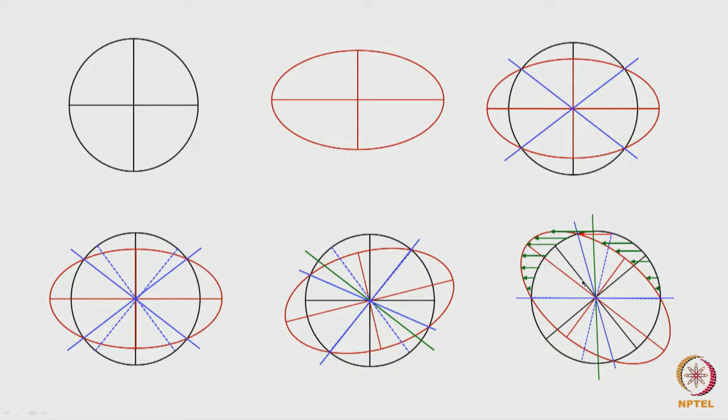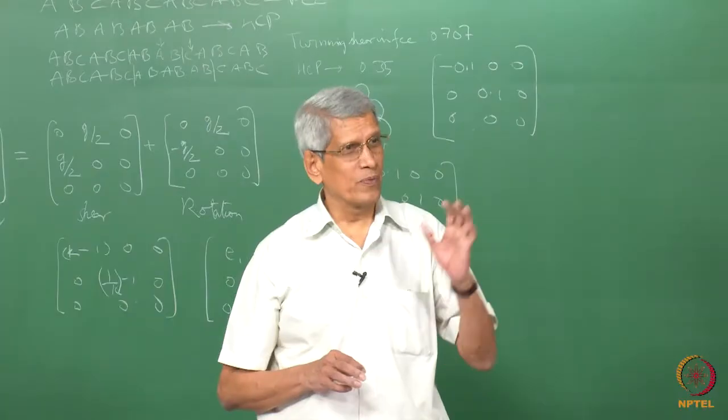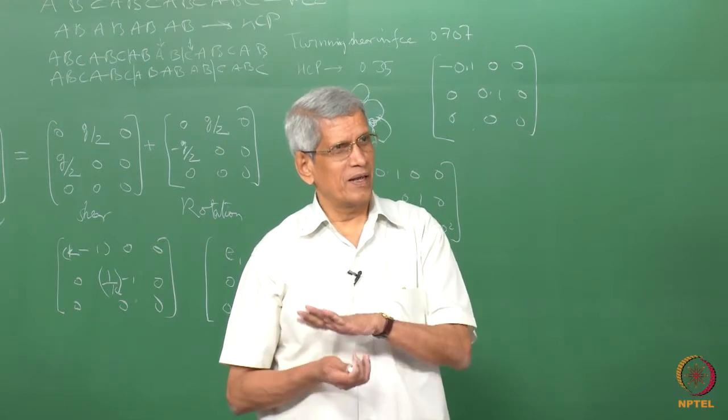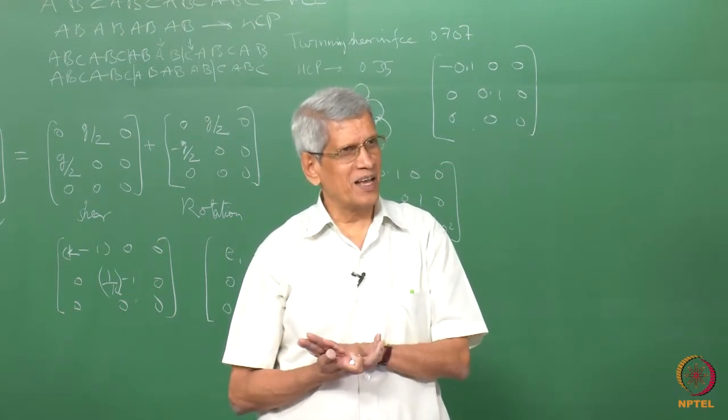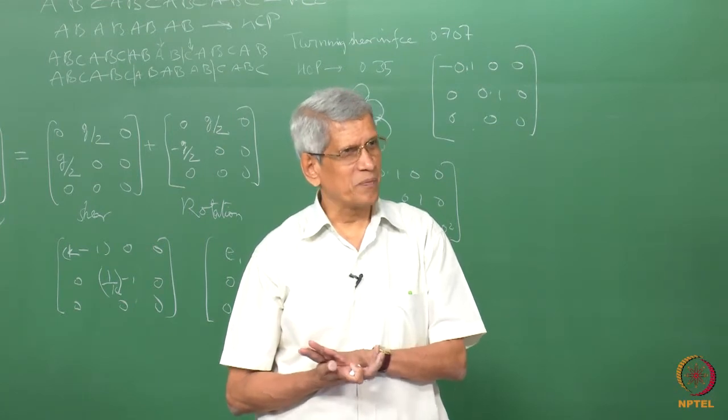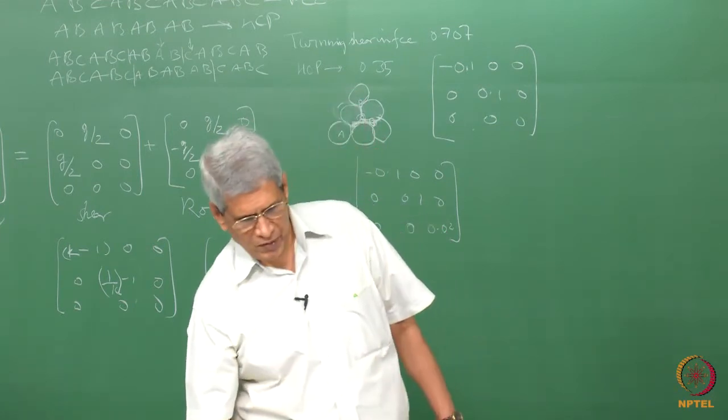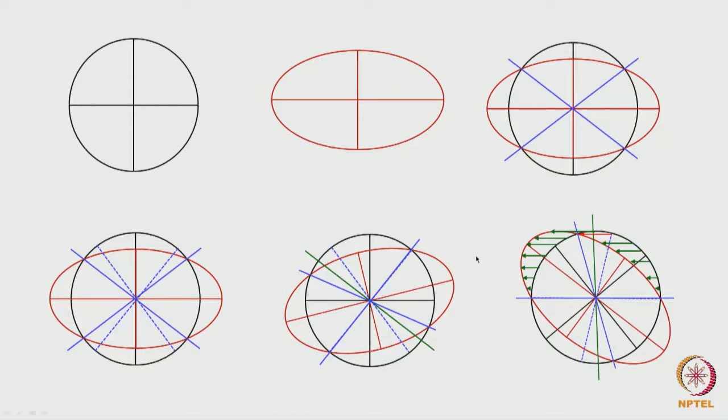So essentially, with the set of these figures, you can understand how we can make a habit plane which is unrotated as well as undistorted. That means that after giving this transformation, some rotation also has to be added. That rotation is also dictated by the shear strain, correct?